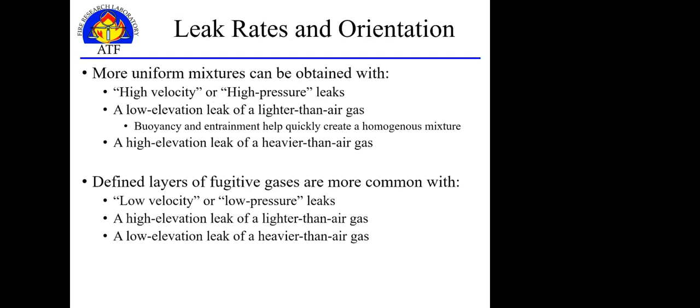Leak rates and orientation. If I have more mixing, I have a more uniform mixture of the gas and air, which allows it to combust a little bit better, as opposed to having defined layers where I might have one side that's a little more lean and another side that is a little richer, and some perfect mixture somewhere in the middle. It's not as stratified.